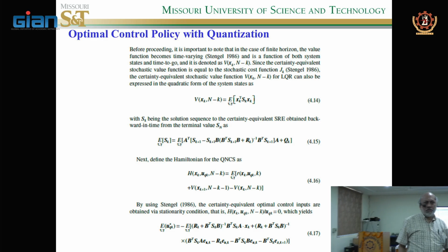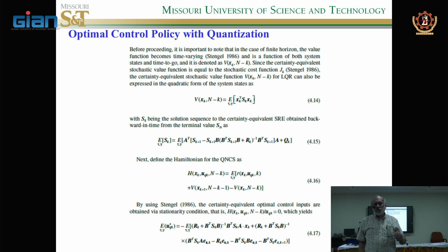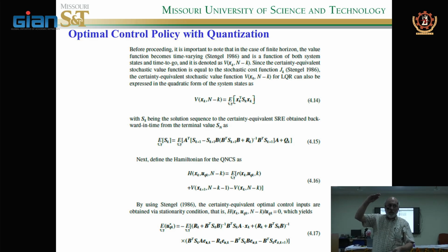Okay, any other questions? You understood what the professor was asking? The quantizer zoom parameter will help you bring it within saturation, because when it goes to saturation there will be a large error. By adding that zoom parameter, you are basically scaling it. It's software scaling, remember, the hardware has a problem. We do that in neural networks. It puts you within the saturation range, then you do the calculation, it comes out, you multiply it by the scaling factor, and that takes care of it.